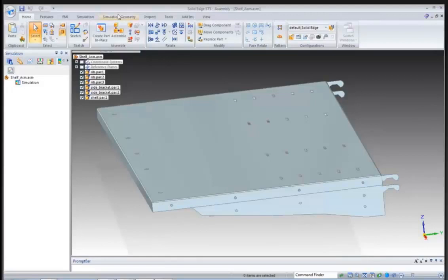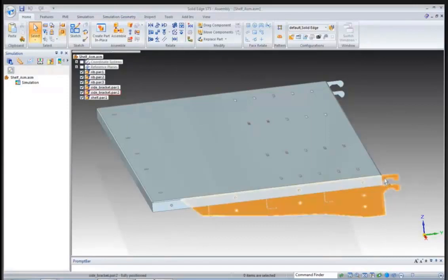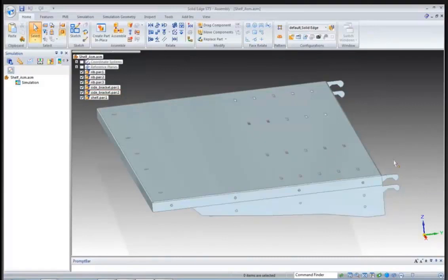You have to be very specific in what you're looking for, and the reason for that is because we make simplifications along the way. So if, for instance, we wanted to look at whether the stress in these brackets is higher than the yield stress, then we would have to include the geometry where this is hooked into, so that rack that the shelf is hooked into.